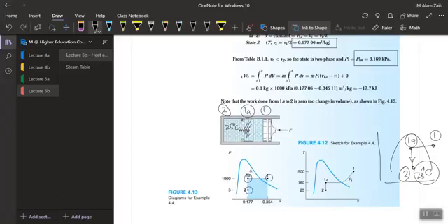So the work done will only be possible in this region, that is the constant pressure process, while there will be no work done in a constant volume process. So the only work done would be from state 1 to 1A. Using the formula, work is m times the integral of P dV. So pressure P1 is given, times the volume V1A, which is the final volume, or half the volume, minus the initial volume, and obviously plus 0 for the 1A to 2 process.